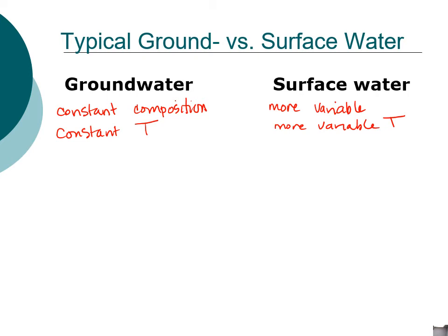So with a large lake, like Lake Michigan, Lake Huron, the intakes tend to be deep, so you can maintain a more constant temperature even though you're using a surface water, and that plays a significant role in operation and the efficiency of your processes, because temperature plays a role or affects efficacy of the process.